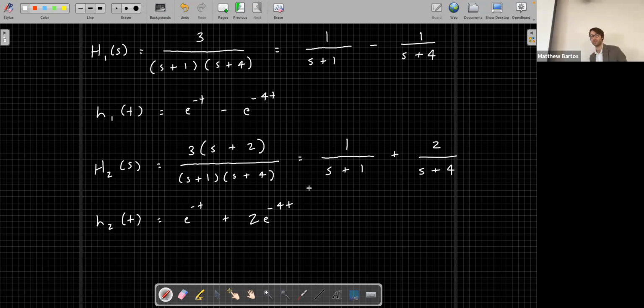Okay, so the general form of the impulse response is the same. Those terms are still the same. It's just that the 0 changed the scaling applied to this second term here. So zeros in general, they're not as fundamental to the system response as the poles are, but they do modify the gain associated with each pole relatively.